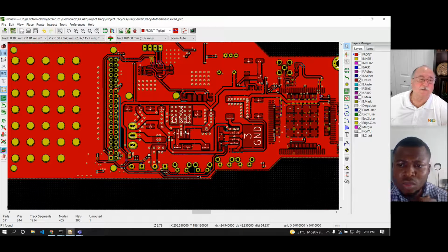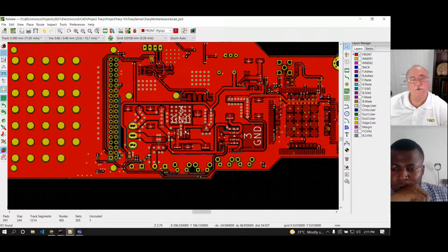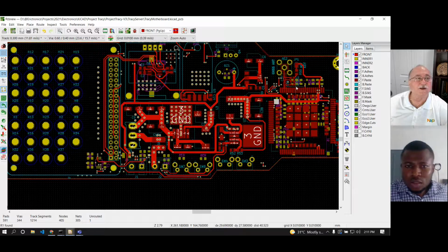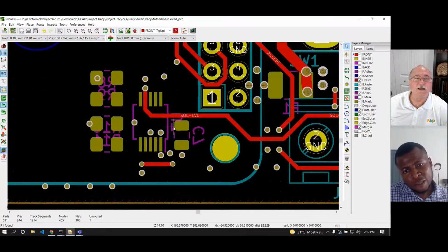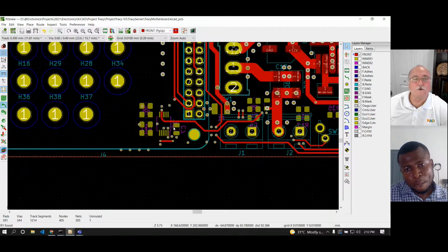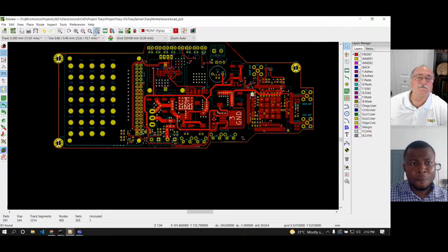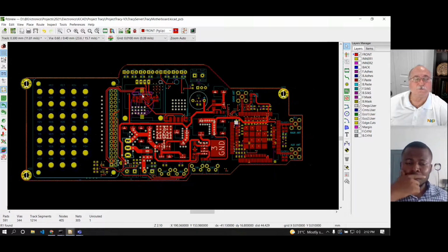And then its job is just to refill the smaller ones that are close to the IC pins. So you get a progressively smaller drop in voltage because each of these containers are bigger, and you take a smaller percentage of the energy, and the slope or frequency of the depletion wave is determined by the geometry of the capacitors instead of the geometry of the IC transistors.